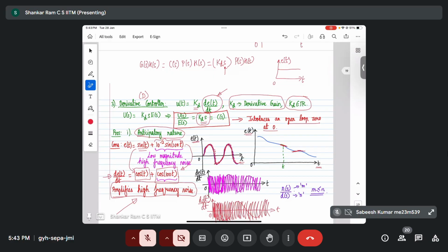Sir, in principle, we can even use ID as a controller, right? Could you elaborate on why that is not coming out to be a practical case? Typically, once again, we will get this intuitive thing, Satish, when you and I design a controller with 3 blocks. You can have various combinations theoretically, no doubt about it. But by and large, one doesn't use I and D and ID, because I may lead to actuator saturation, and D leads to spikes in the input if the error changes quite fast.